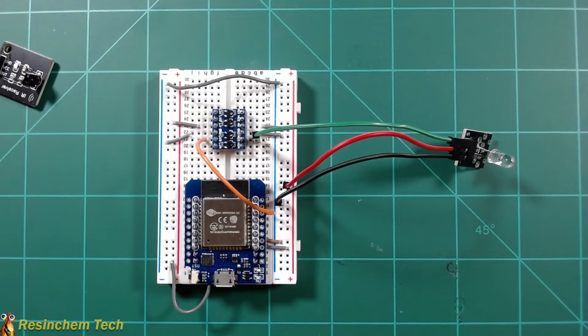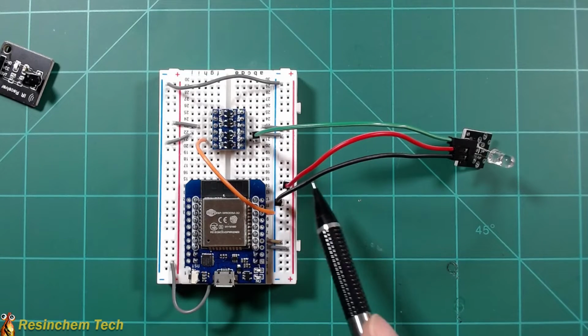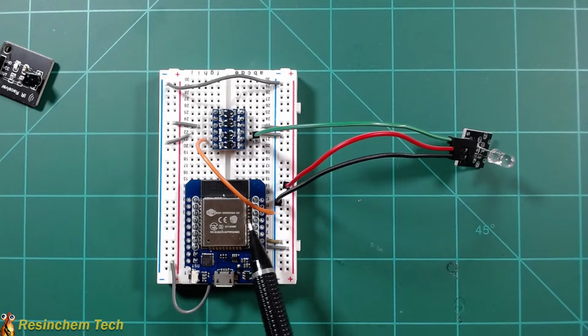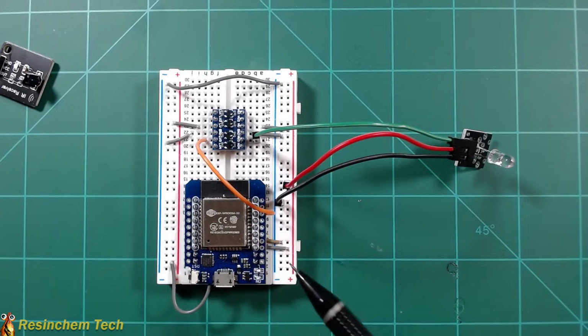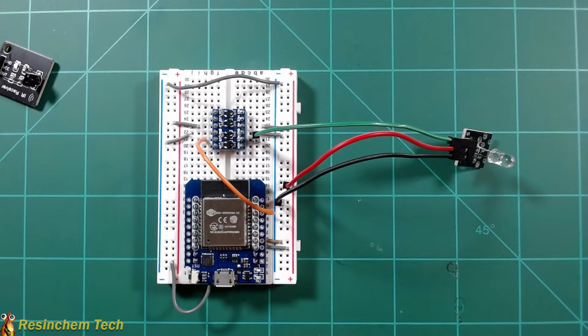Now the wiring on this is really simple, so I won't go into a lot of detail. If you're not using a logic level shifter, it's 5 volts and ground and a data line from a single GPIO pin on your ESP controller. That's all there is to it. Again, I'm adding the logic level shifter. Whether it really helps or not, again, I don't know. But you can find a complete wiring diagram for this. Check down in the video description.